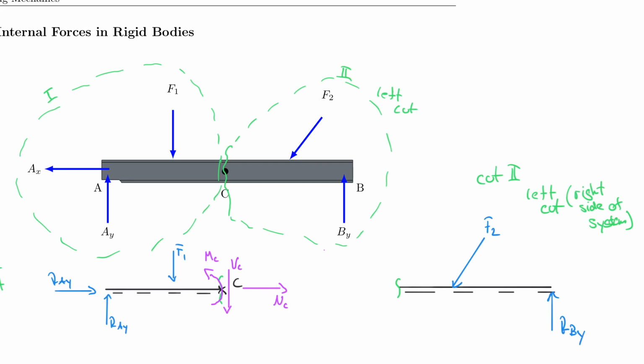You can see that right now. So I have to bring in my external forces, which ultimately are the internal forces. But because I made the green cut there, I now actually have external forces, a vertical one, a horizontal one, and a moment, if you will. And of course, they now have to balance whatever I have defined here. So therefore, they point upwards, they point to the left, and they rotate clockwise in this case. And of course, they are also N of C, V of C, and M of C. And now the left side is in balance with the right side.